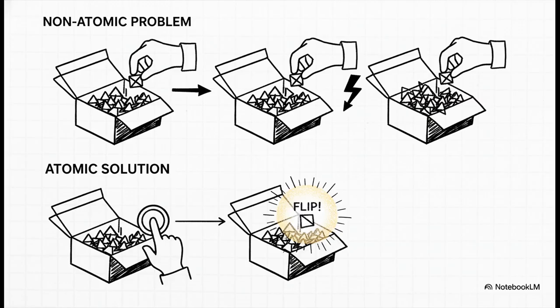See, normally to change just one bit, a program has to read a whole chunk of memory, carefully modify that one bit, and then write the whole chunk back. If another process interrupts that sequence, you can get all kinds of errors. With bit banding, you just write to that bit's special address, and the hardware does the entire operation instantly and safely. No extra code, no risk.